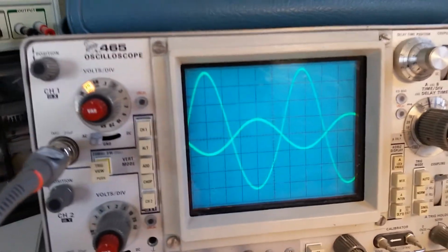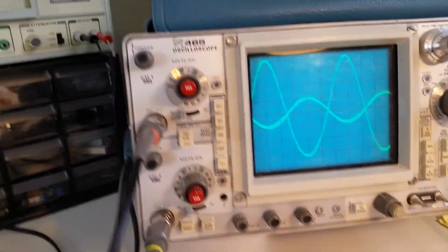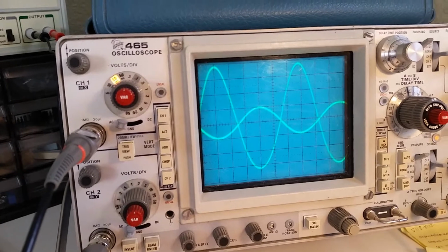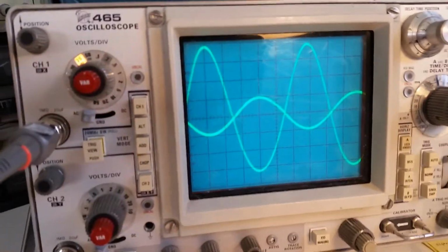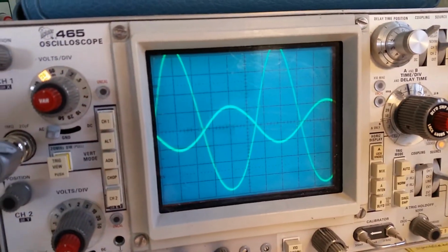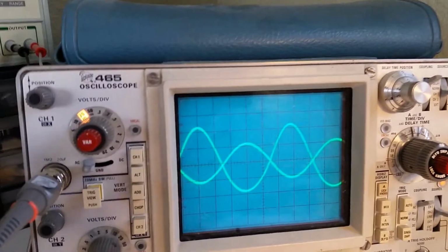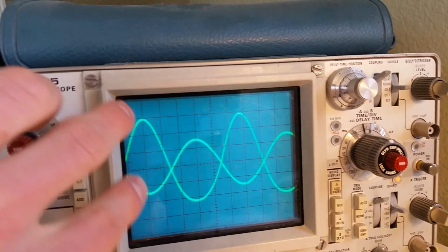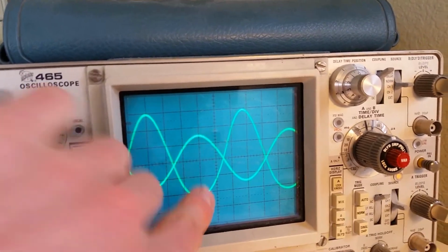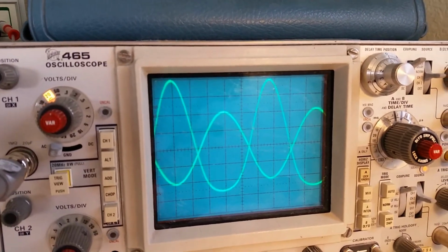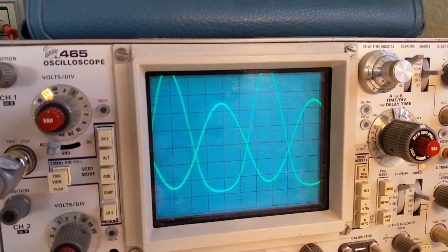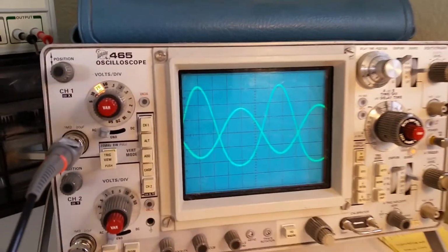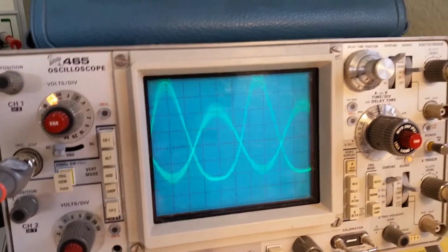That's a gigantic output. I think I calculated the gain to be about 87. And as you can see, there's a bit of distortion there. It's not perfect. Let me bring that up just a bit more. Yeah, see, a little bit of second harmonic because it's asymmetric. You got a little bit of rounding at the bottom here. Yeah, soft clipping. That's interesting. But that's typical of a stage like this.